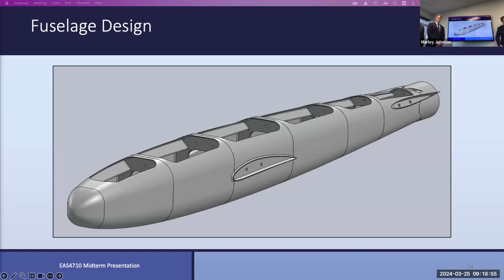Particularly in a fuselage, where the bending is going to be down. For the most part, you're pulling positive G's, so your fuselage is bending down. So you're not putting compression in things, you're not wanting to buckle things at the top. So if you're going to have them, the top is the right place to do it. If you're doing the wing, then the right place to go is the bottom section, where you're primarily in tension.